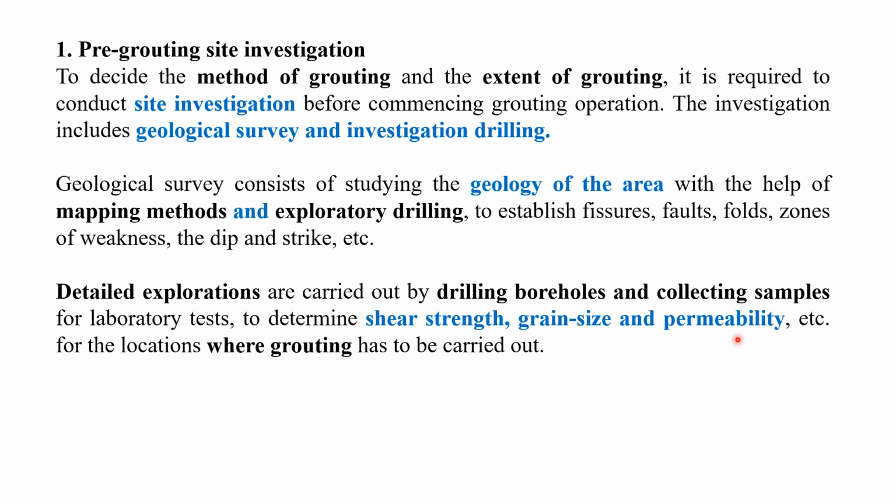Whenever you talk about the permeability, whether we have to make the soil impermeable to control the seepage, or even permeability also gives the idea whether the soil is cohesionless or cohesive. That idea we can also get by the permeability test. So these parameters come under the site investigations, which we have to carry out before grouting.